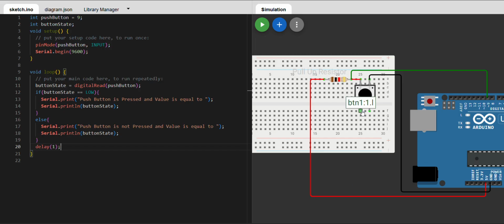Then the output that we have taken from this point to the ninth pin will be 0. In the practical case we won't get exactly 0, but less than 5 volts, and it may be from 0 to some 1 to 1.5 volts.